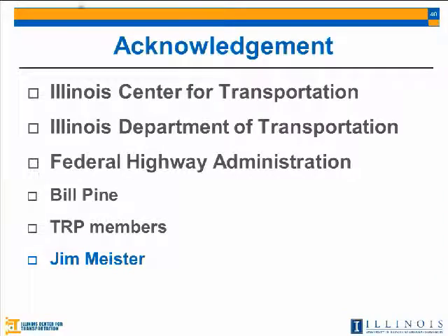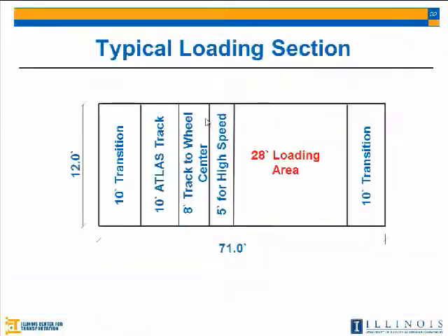Well, I missed the beginning, Ibrahim. What's PPA again? It's polyphosphoric acid. It's a liquid mineral polymer, which is used as a modifier, added to binder. For some types of binder, it bumps the high temperature part, and for some other binders, it bumps both the high and the low temperature parts of the PG. It is generally not used to control moisture damage, but we would like to use it for this study and see how it performs.